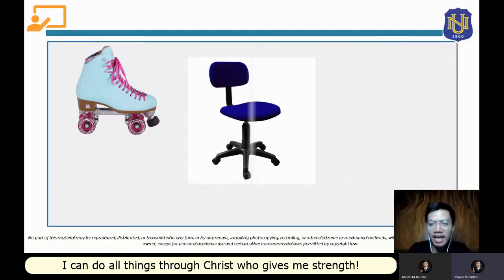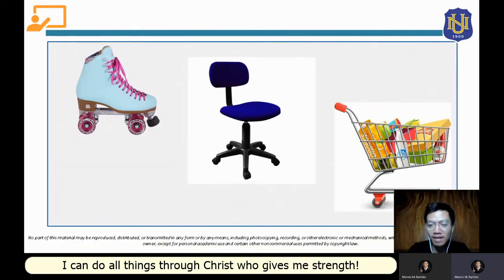So these are real life examples of roller supports. This shoe is supported by these rollers, and the support that it provides is a normal force. So that normal force will be perpendicular to the surface where this roller is lying. Same with these rollers and this roller. So these are examples of rollers in roller support in real life.